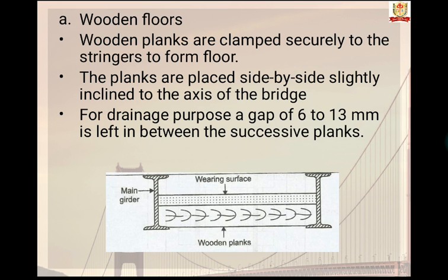Wooden floor. Wooden planks are clamped securely to the stringers to form a floor. The planks are placed side by side, slightly inclined to the axis of the bridge. For drainage purposes, a gap of 6 to 13 mm is left between two successive planks.